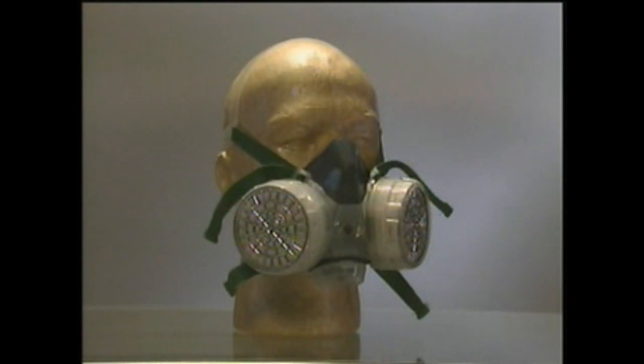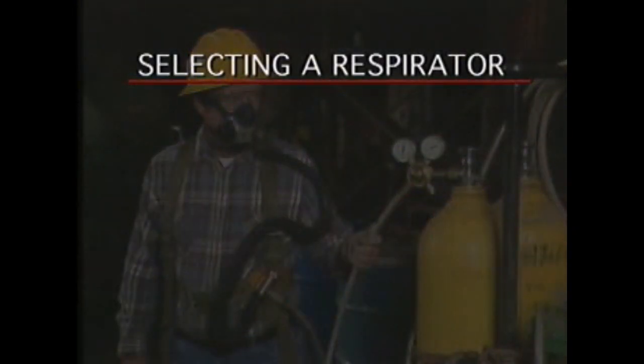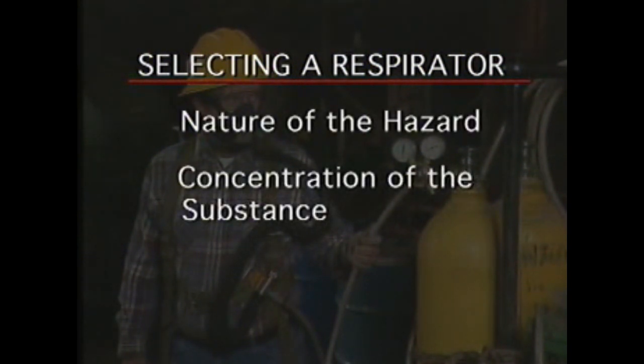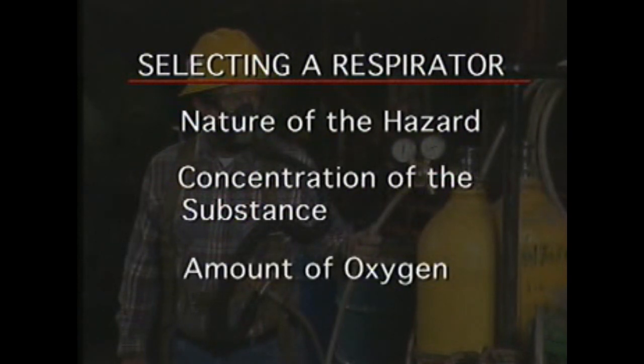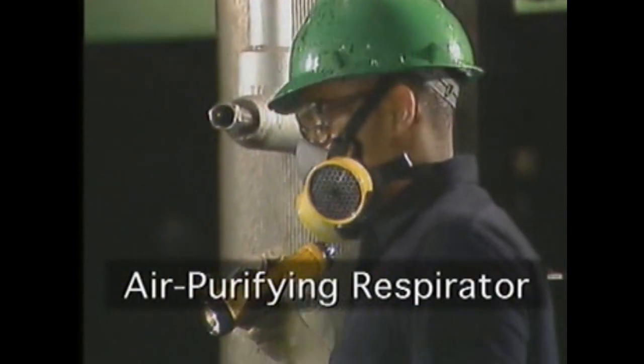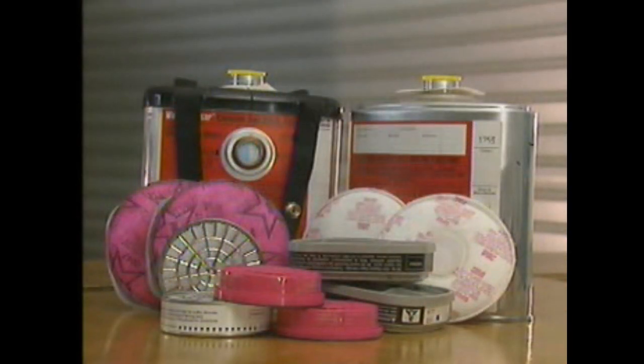There are different types of respirators. Each type is designed for a specific application. The one that you choose depends on such things as the nature of the hazard, the concentration of the hazardous substance, and the amount of oxygen in the atmosphere where you're working. One type of respirator is an air purifying or filtering respirator. This type uses either a half or full face mask with replaceable filter cartridges to remove hazardous substances as you inhale. Some air purifying respirators use a canister containing a filter or an adsorbent material to remove hazardous substances.